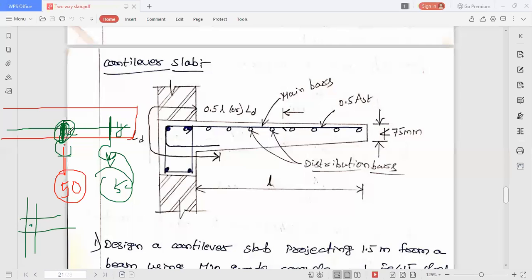You know what you mean by cohesion and adhesion. So the adhesion between the steel embedment and the surrounding concrete is resisting 50 kgs. It's not hook and not concrete. Okay, and as this adhesion area is very less in first case, it is failing. But in the second case, as the surface area of the steel with concrete is increased, the adhesive force, that means the bond force, will increase.